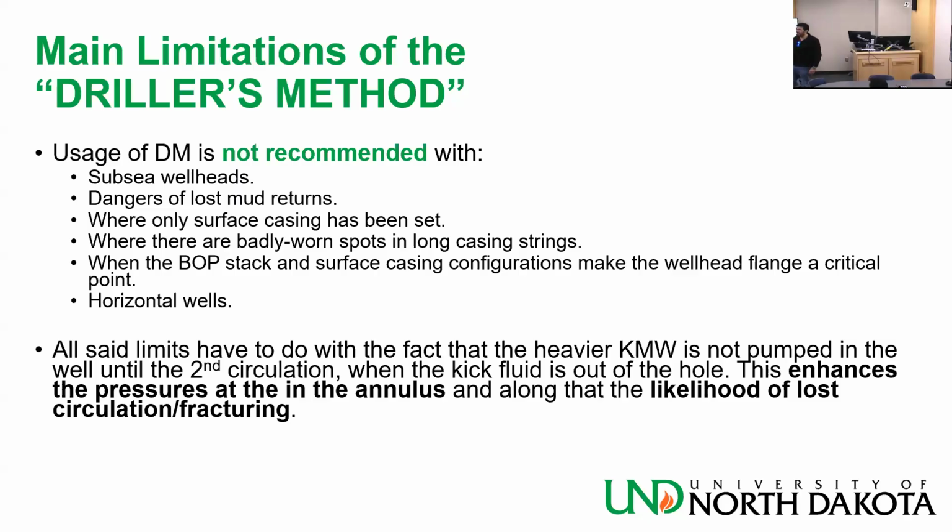If the pressures are higher, I'm closer to MASP than with other methods. That's why I don't want to use that method there. Doesn't mean I cannot use it.